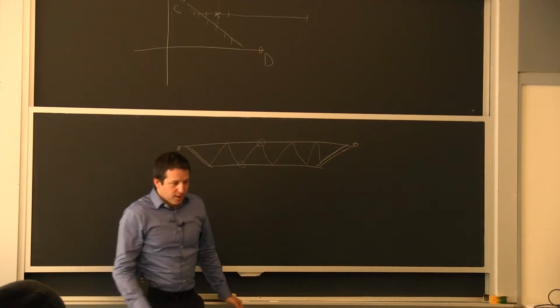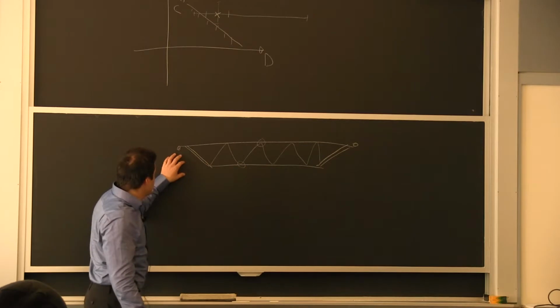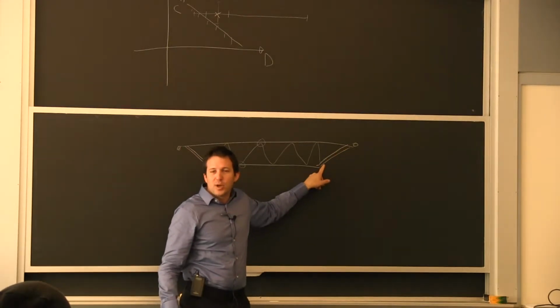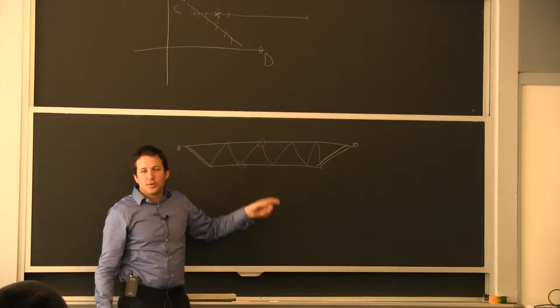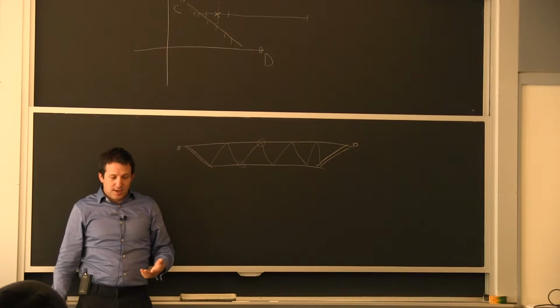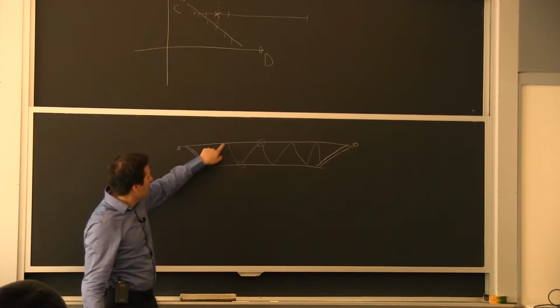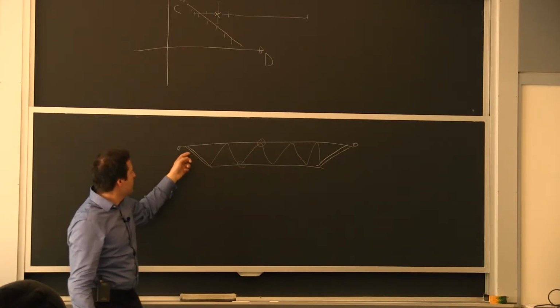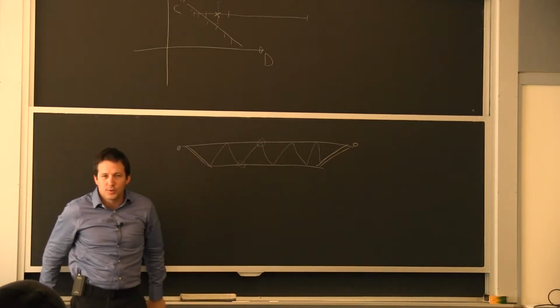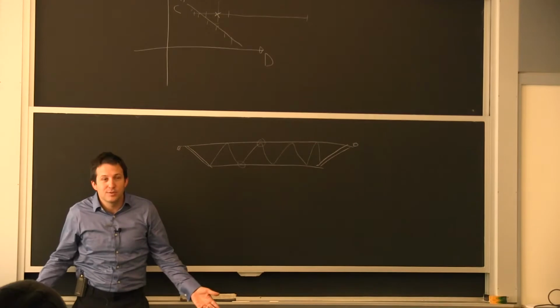So what a lot of joist manufacturers do is they make that first connection in a different way than they do the others. If you remember the flare bevel design that I've talked about quite a bit, they could have this round bar going around, and here they put 2 flat bars that you weld just on the side of the tube. These are easy fillet welds to do.